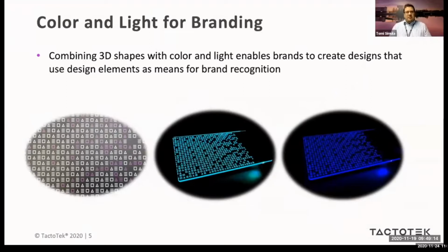It would, of course, be very attractive to be able to get away with a very simple solution where you just slap a current limiting resistor between an LED and the power supply, but the result that you get this way is hardly ever good enough for any more strict requirements than simply having something. So a smarter driving solution is typically needed.